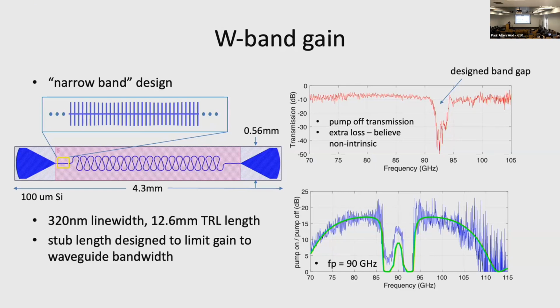But yes, when you apply a current, and especially with these high kinetic inductance materials, Mattis-Bardeen is not going to be precisely right. You have a smearing of the gap, and so it's a slightly more complicated calculation, which can be done. In the regime that we're working with here, that's not a very large effect, but as you get closer to the gap frequency, then you will start to see some deviations.